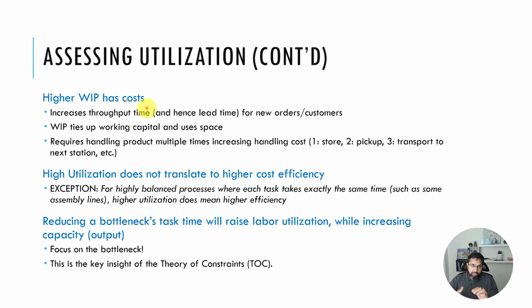So every 30 seconds, every station is done. Every station just takes 30 seconds to do their job, or 1 minute. So the assembly line has a pace. It's a paced assembly line. Every 60 seconds or 30 seconds or 2 minutes, things move from one station to the next. So it's running at that same pace. And you have divided the work so that each station's work takes exactly the 30 seconds or 60 seconds, whatever the takt time is. Takt time is another word for cycle time.